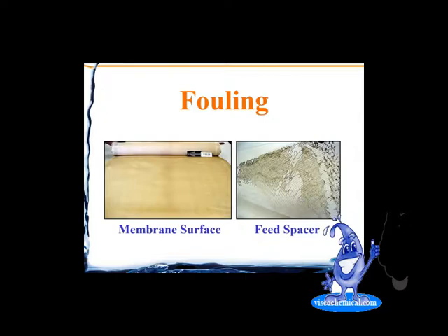On the left, there's a picture of fouling on the surface of the membrane. And in this case, the feed spacer has been removed. And here is fouling showing that it's plugging up the feed spacer. So the feed spacer would be laying on top of the membrane.